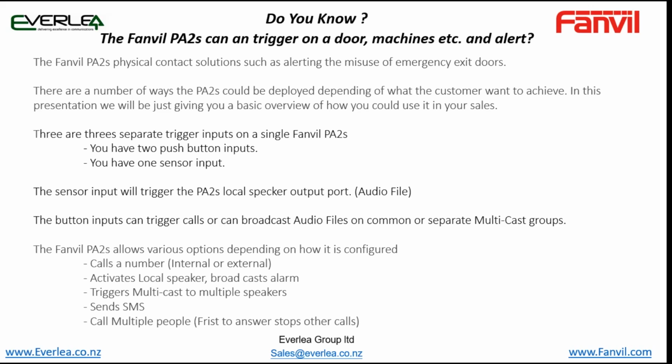The sensor input will trigger the PA2's local speaker output port. The file that can be played is a WAV file, so can be any audio requirement. The button inputs can trigger calls or can broadcast audio files on common or separate multicast groups. The Fanvil PA2 allows various options depending on how it is configured. It can call a number, activate a local speaker, broadcast alarm, trigger multicast to multiple speakers, send a SMS or call multiple numbers at the same time.